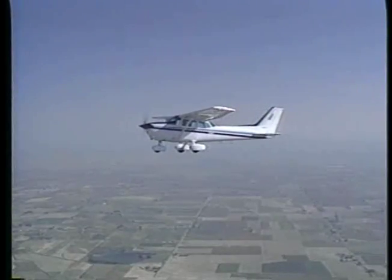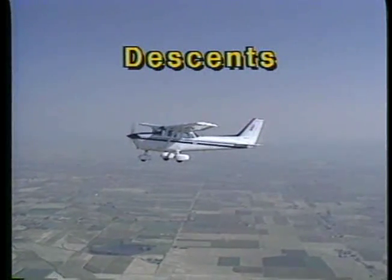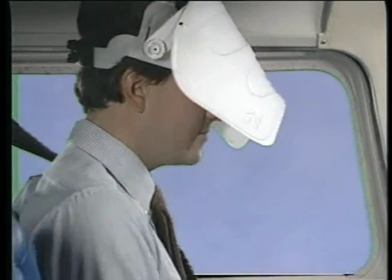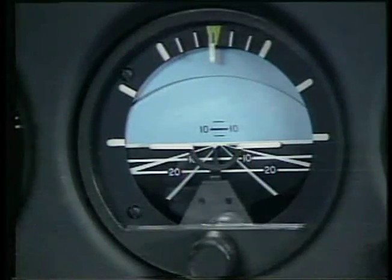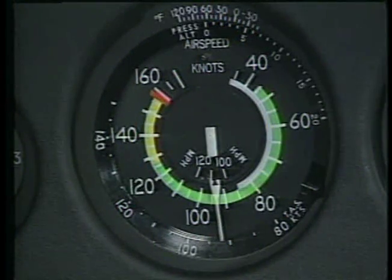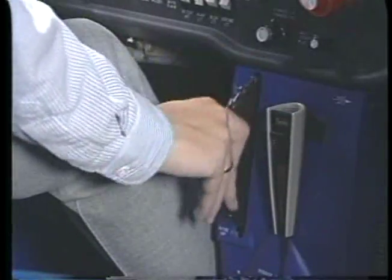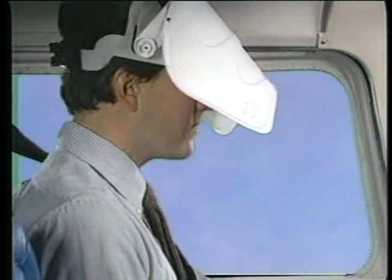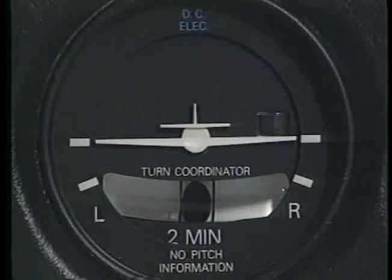With the airplane established back at straight and level, let's go ahead and look at how to descend by instrument reference. To enter a constant airspeed descent, establish the desired airspeed by reducing power to the predetermined setting and maintain altitude. As you reach the desired airspeed, lower the pitch to maintain the airspeed and trim for the descent. Correct any deviation in airspeed by adjusting the pitch attitude. Use the bank control instruments to maintain directional control during the descent.